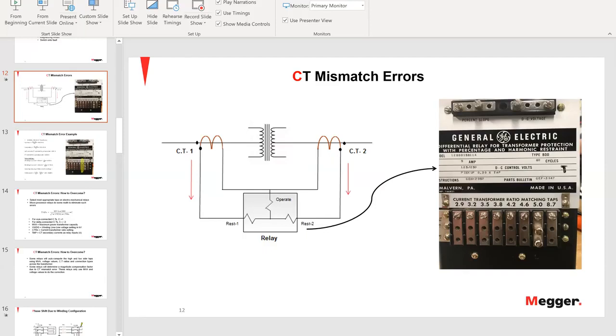That's a type of protection that is used on a lot of systems, actually, that prevents the successful culmination of a closing operation when the relay or the protection system detects that the switching is being done and a fault is present in the system. There are several implementations of that protection function. I guess that should answer the question.